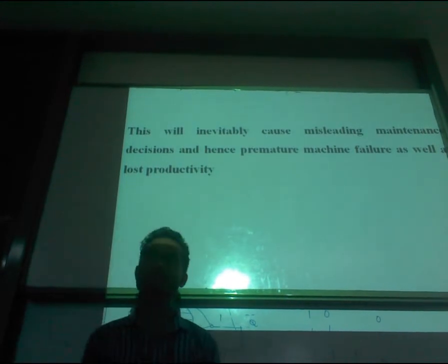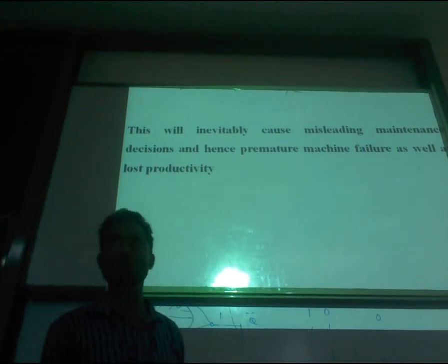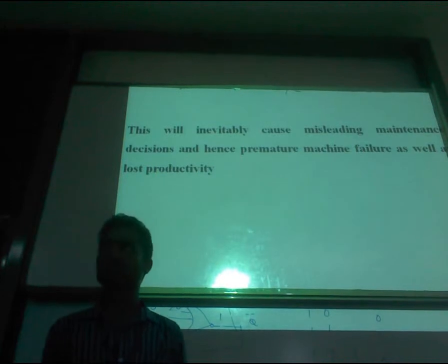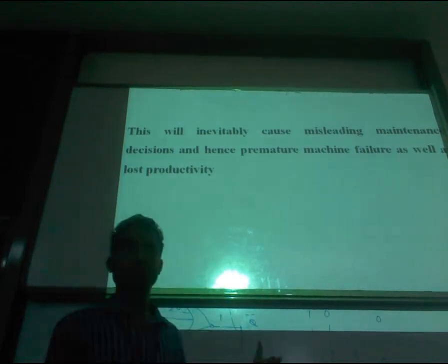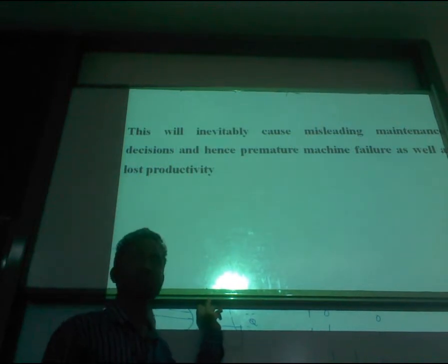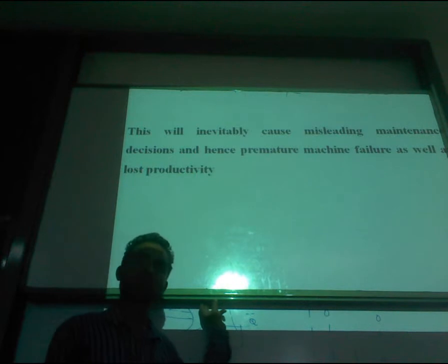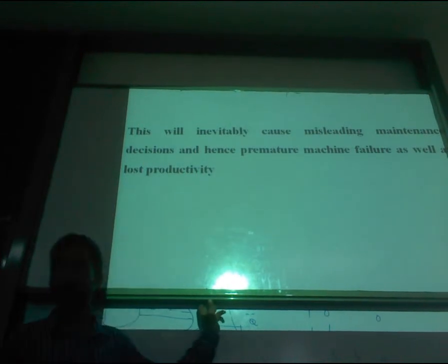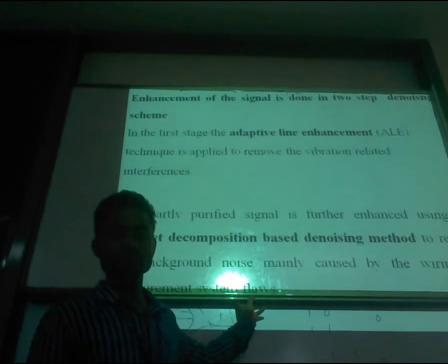If we feed the signal from the oil debris sensor directly to the operator and he reads it directly, he will surely take a wrong control decision. He will prematurely assume that the engine has failed, though the engine is working properly. Since there is a lot of noise in the input signal, the driver can't decide whether the engine is running with smooth performance or whether wear and tear is taking place inside the engine.